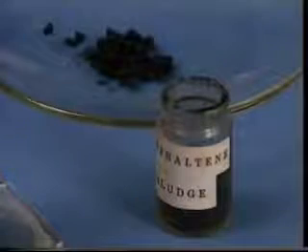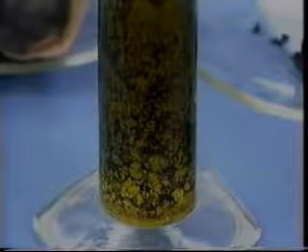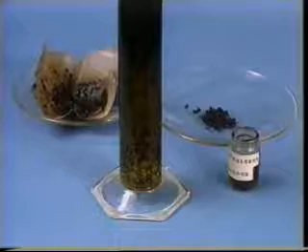Surfactants can sometimes minimize sludge problems. Sludge is a solid that forms when acid contacts asphaltic crude oil. Sludge is extremely difficult to dissolve and will adhere to reservoir rock, causing a decrease in permeability.